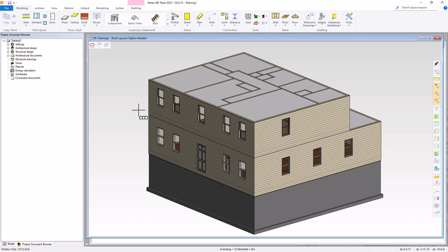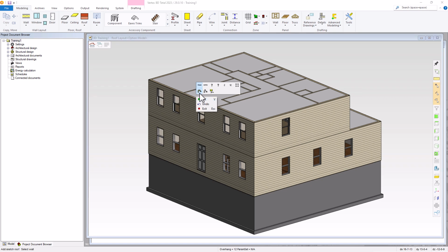Right mouse click to bring up the roof generator menu. In this menu you have trusses, if we want to start with the truss system. We have the rafter button if we want to add rafters. Next we have edit roof parameters. We can assign a roof overhang. There's also a couple of presets. This one's a 2-inch roof overhang, and this is a 12-inch roof overhang.